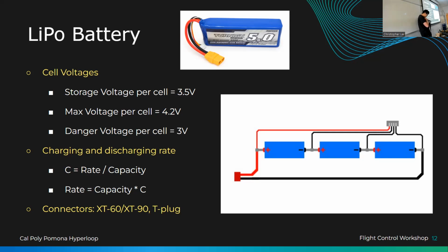That's not a voltage tester. This is. So if I don't know exactly what voltage my battery is, because again, if it gets too low voltage, it'll explode or burn on fire or just swell up and be extremely dangerous to watch. So all you gotta do is get one of these things. They're like a buck on Amazon, and you can plug this JST cable. Every LiPo battery, or a good one at least, should come with one of these because this cable connects to every single cell. So it will tell you the voltage that's inside every single cell, right? Again, if the voltage is too low, you're in danger.